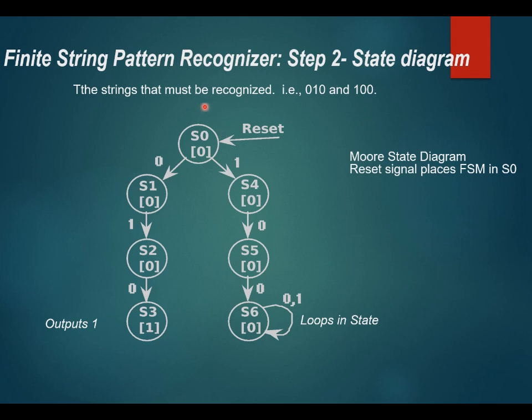You can start with the initial state S0, which means no bit is detected. Since this system has only a one-bit input, the input at one time is either 0 or 1. So we just need to consider 2 outgoing branches from each state. S0 receiving 0 means this 0 represents the first bit of the 0, 1, 0 string, so you can move to S1.